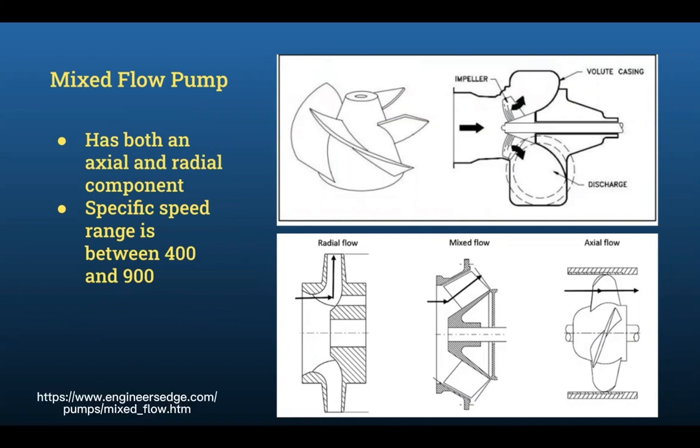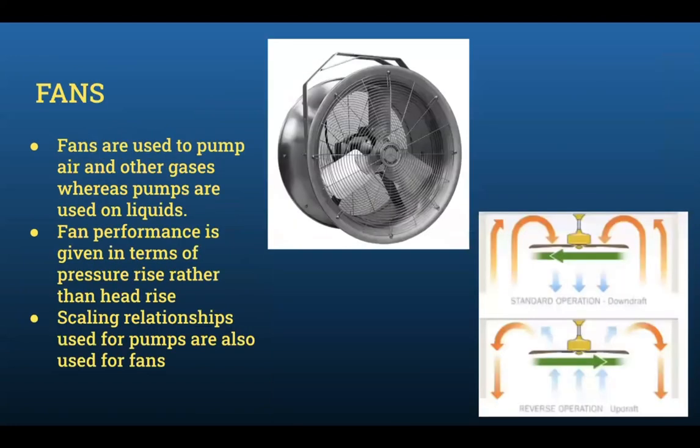A biomedical application of pumps would be the LVAD, which supplements a diseased heart and can either use centrifugal or axial flow for continuous flow of blood. Now, pumps and fans operate the same way, but pumps are used for liquids while fans pump air and other gases. But rather than the head rise, the pressure rise is used for fan performance data. The scaling relationships used for pumps are also applicable to fans,